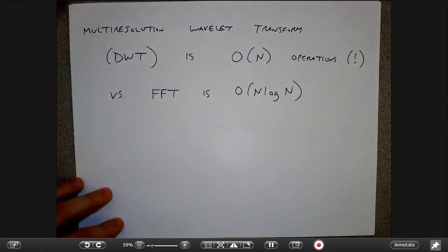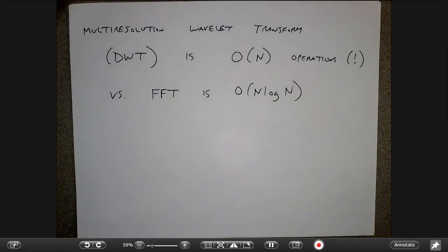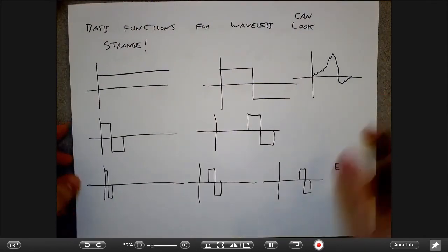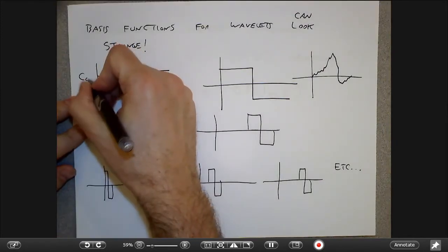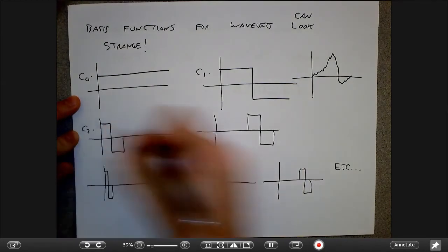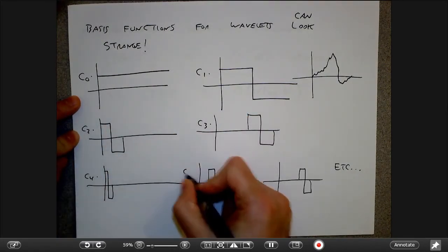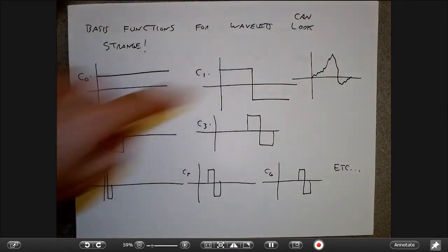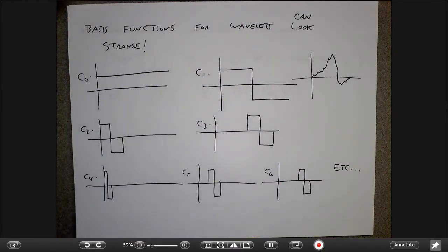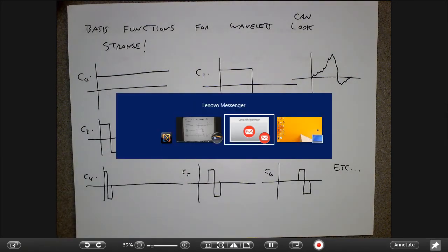Right. So let's talk about that for a second. In the 1D case, what I'm doing with a 1D wavelet transform is fundamentally representing my original signal as some coefficient times this plus some coefficient times that. You can think about it as separating my original signal into a sum of basis functions, in exactly the same way that we drew sines and cosines for the Fourier transform. For an image transform, you're basically doing a wavelet decomposition both in the row direction and the column direction. It's probably easiest just to show you; I'm sure we can find a picture of it.